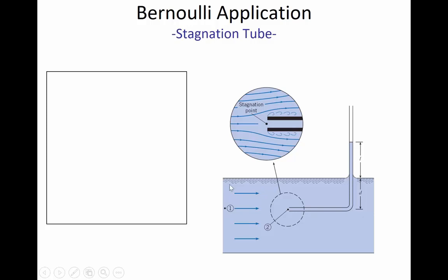And what we know from Bernoulli's equation is that the energy is going to be changing form. And so here's Bernoulli's equation where we've eliminated the elevation term because 1 and 2 are on the same horizontal plane, and so the z's are equal. This is written so that each term of the equation has units of pressure, so pascals or newtons per meter squared. Remember, in the other form that we sometimes use, each of the terms has units of meters, and that's when we would simply divide by gamma for each of these terms. But here we're just going to write it in terms of pressure.